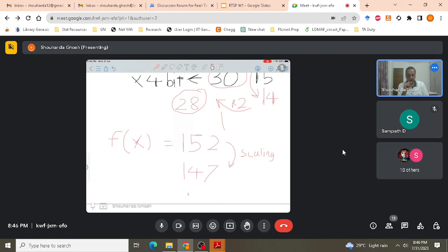So what is happening at the end of the day is you are saving your hardware because you are using a lower number of bits, and also since it is a human application. Let's suppose this is being used in video conferencing that we are seeing. The pixels you can see over here are very much the same. So some algorithm might not be working to very high precision; it might show this as 155, this one as 156, whereas these two could be 160 and 163. But it does not matter to you because you see both of them as the same. So we are getting an approximation, we are incurring an error, but that error is not very harmful for the application; that error is adjustable for us.